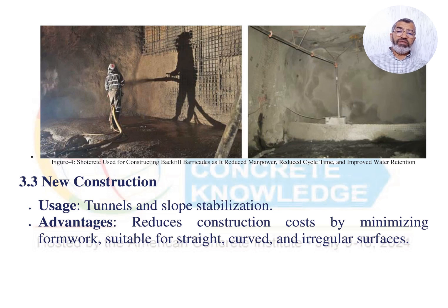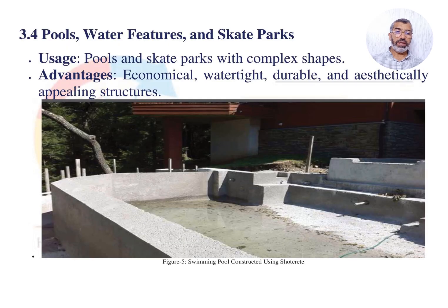Now another application for the shotcrete is in new construction, especially to construct tunnels and also for slope stabilizations. The advantages here are to reduce construction costs by, of course, minimizing formwork, and it is also useful for straight, curved, and irregular surfaces and shapes that are hard to implement using conventional concrete.